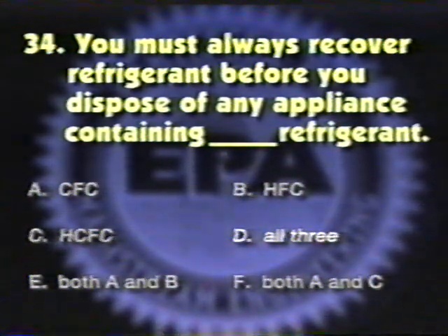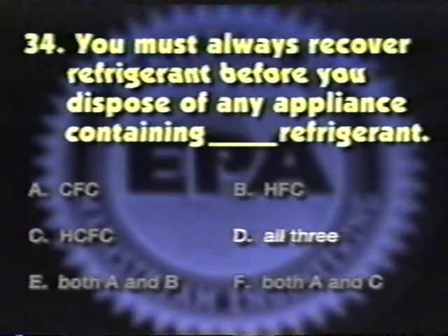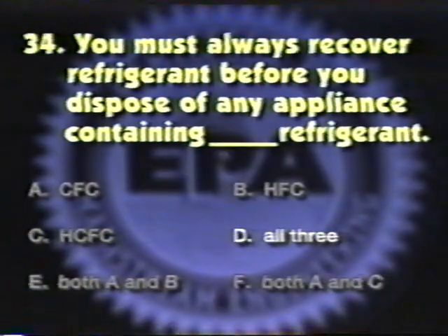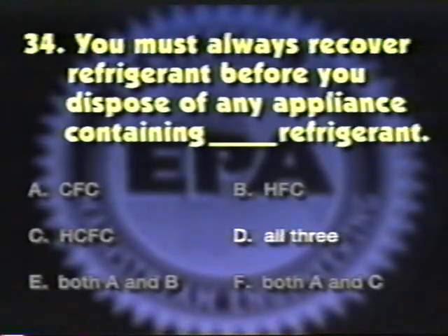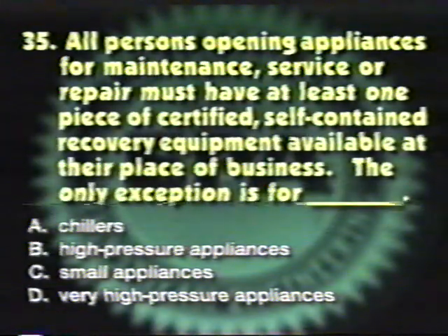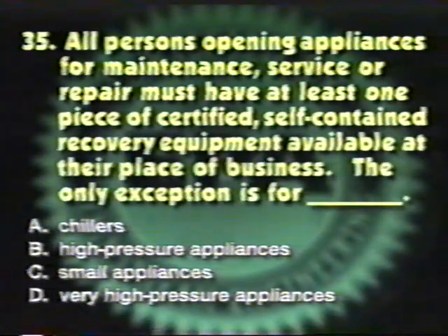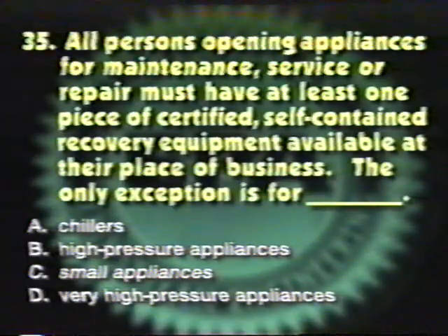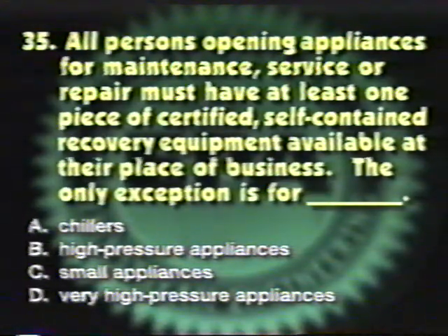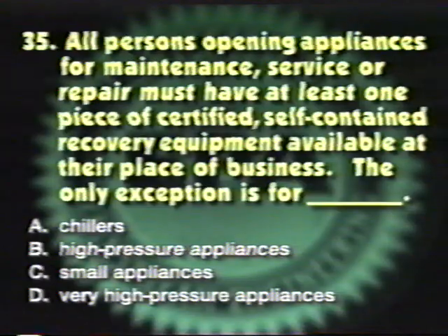The answer is D. All three. Before you dispose of any appliance containing a CFC, HCFC, or HFC refrigerant, you must recover the refrigerant. All persons opening appliances for maintenance, service, or repair must have at least one piece of certified, self-contained recovery equipment available at their place of business.